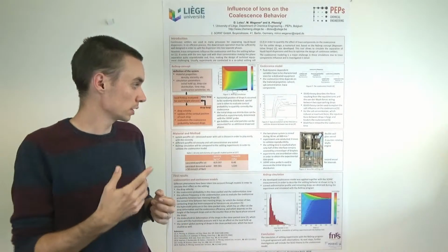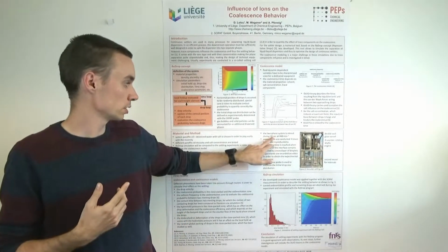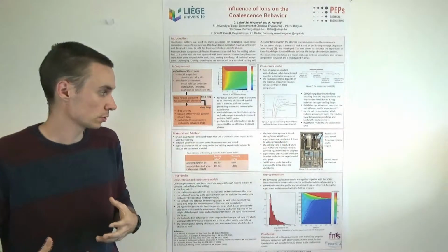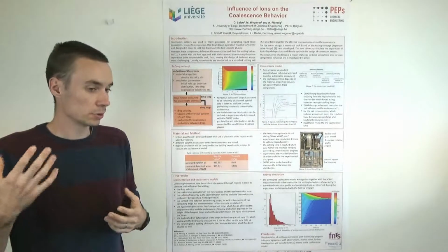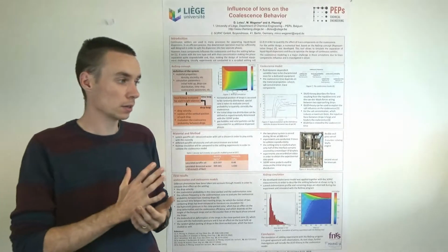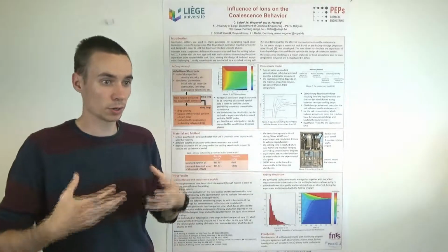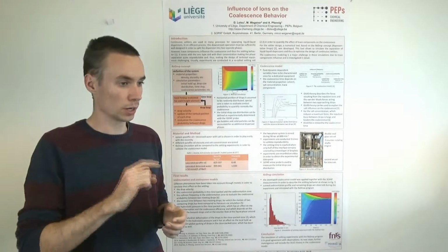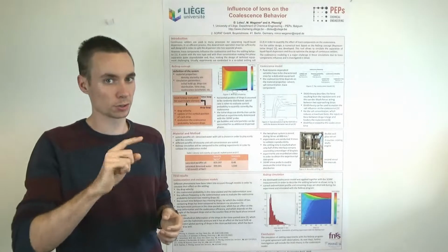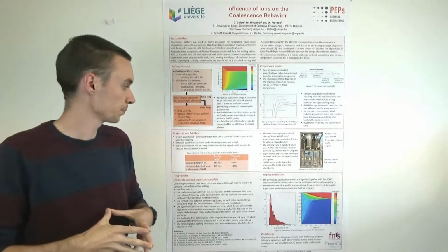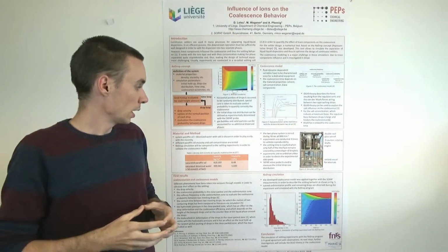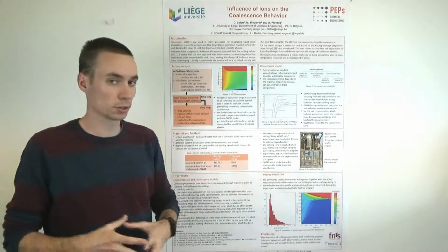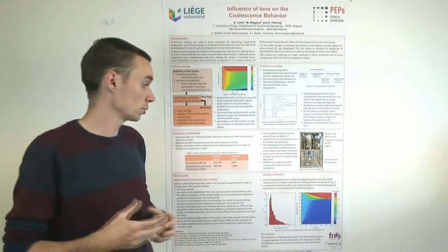They rotate for 30 seconds at 800 rotations per minute to create the dispersion. Then, when the dispersion is created, I stop the engine and I record the settling with a movie camera in order to localize the sedimentation curve and the coalescence curve. I will show you the result after. I also use the SOPAT probe to measure the initial drop size distribution, which is an important parameter for my simulation.